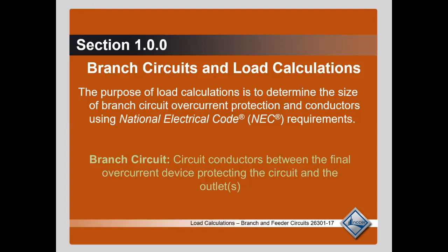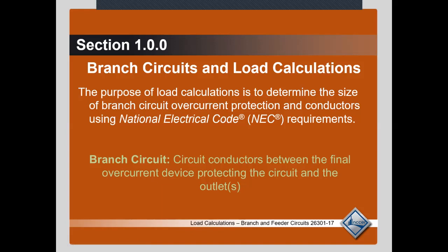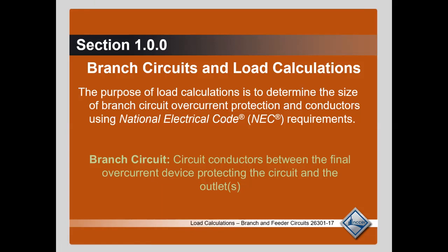Now, if that's continuous use, you've already derated it now. You've got to derate it to 80% of its maximum size. So what is 80% of 30? You can take a guess. It's going to be about 25. Okay, so about 25 amps of power, which that nameplate rating says the maximum, and that's continuous. So I would run a number 10, just because it says right here, number 10, non-continuous use is good up to 40 amps of power. So that's the safer way to go.